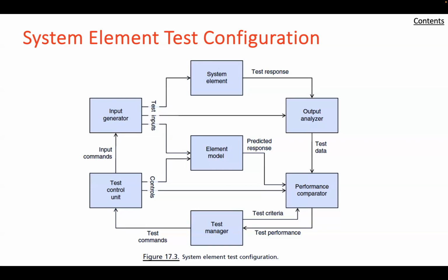These tolerances must allow for the degree of precision of a production machinery, as well as the variation of the size of standard bolts. If the specified tolerances are too tight, there will be excessive rejects in manufacture. If too loose, there will be occasional misalignments causing fit failures. Personnel errors are a common source of test failures and one that can never be completely avoided.